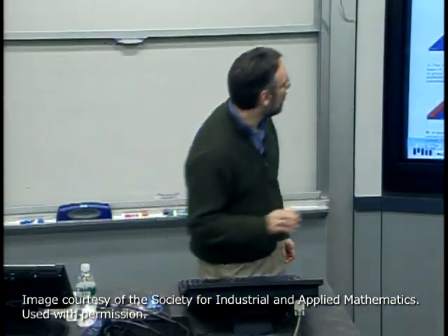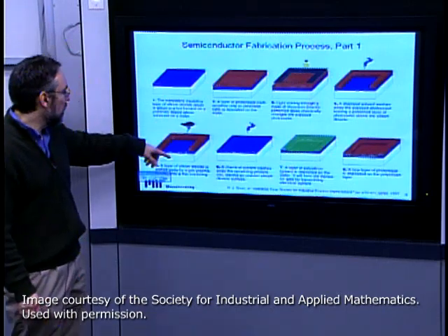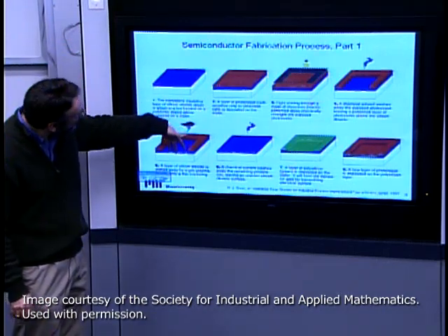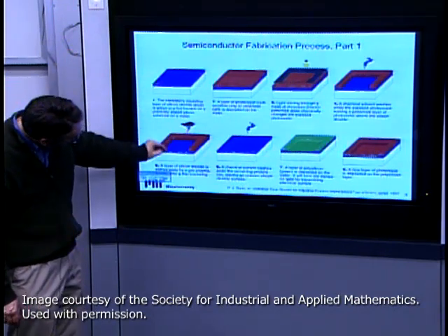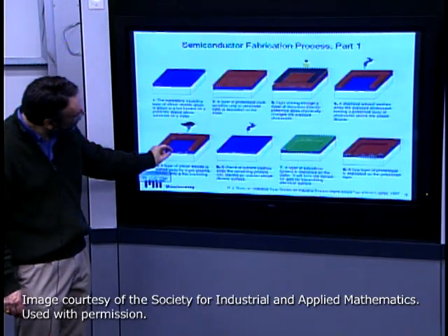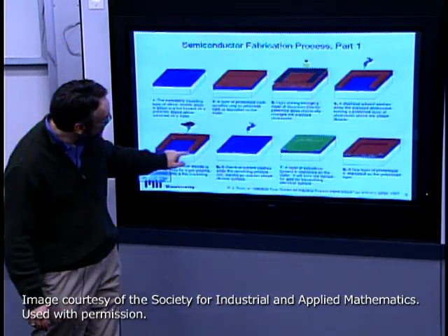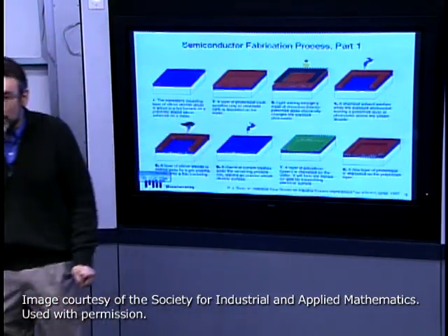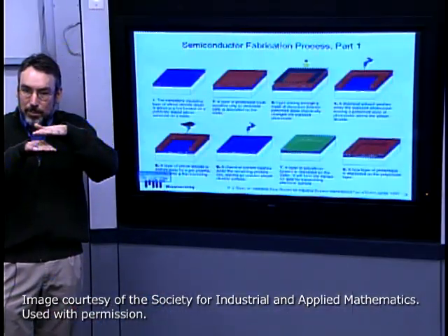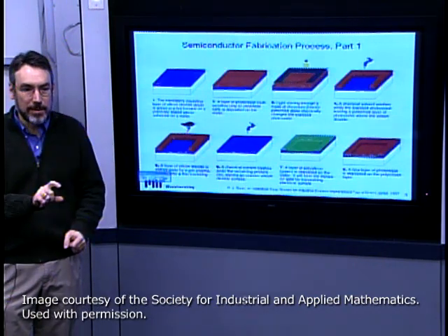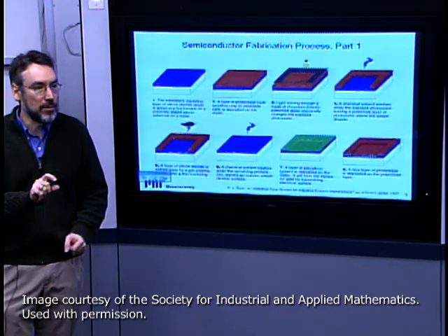Now in this picture, what they're trying to do here is show that we are partially etching some silicon dioxide layer away, apparently leaving a small remaining level or layer of silicon dioxide. So you can sort of see that shadow down in there. What they're trying to show in this case is they're leaving this thin silicon dioxide layer that is going to be that insulator between the gate electrode and the silicon that we talked about in the final structure.